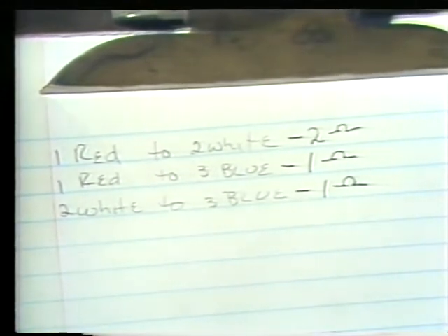Suppose you check the nameplate of the motor and it didn't show what kind of connection the motor has, and you can't seem to find the manufacturer's manual. Well, there's really no problem. Just test it as if it were delta connected. That way, you look for balanced resistances rather than just continuity. By looking for a balance of resistances, you'll find out if there's an open, regardless of which kind of motor it is.